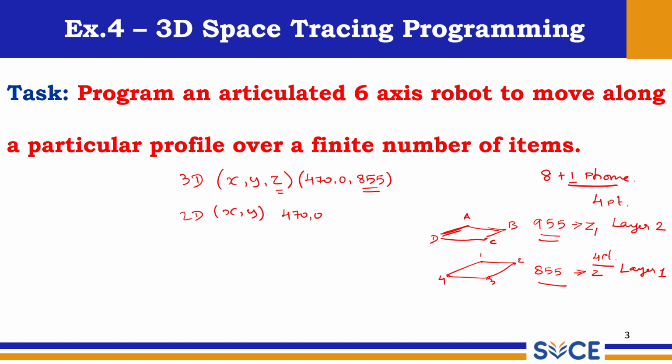But you need to be very cautious when you program, so we'll go through a simple example. This is for the case of a prismatic part, like a cube. How do you do it for the case of a cylinder? We do this by means of the command: P1 starting point, P2 passing point, and P3 end point.